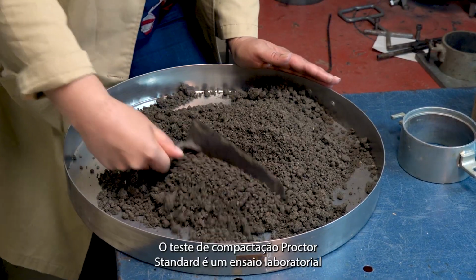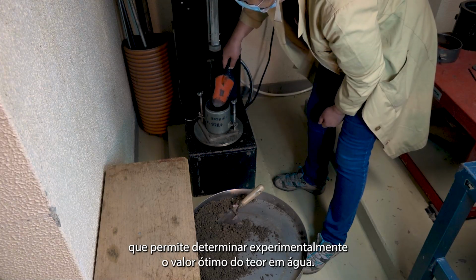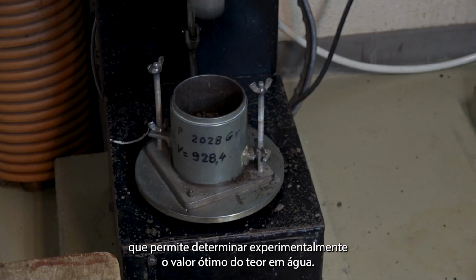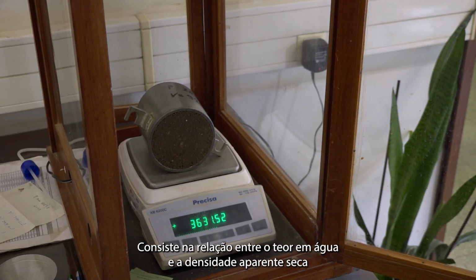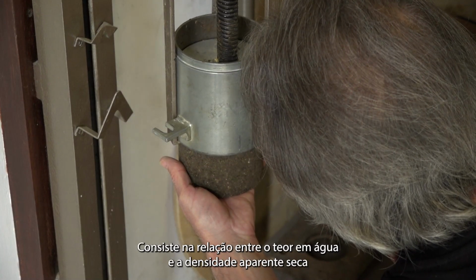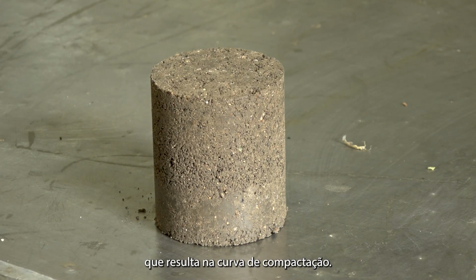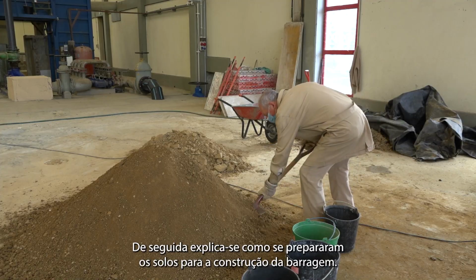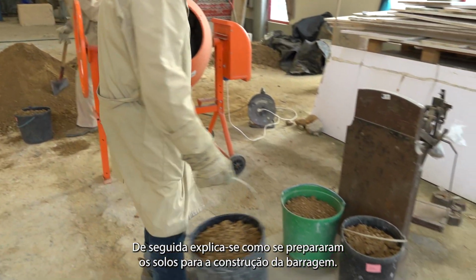The standard Proctor compaction test is a laboratory method to experimentally determine the optimal moisture content. It generates a relation between moisture content and dry density, called compaction curve. We now explain how to prepare the soils for the dam's construction.